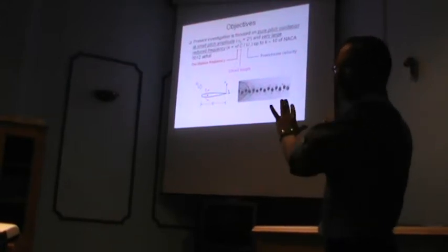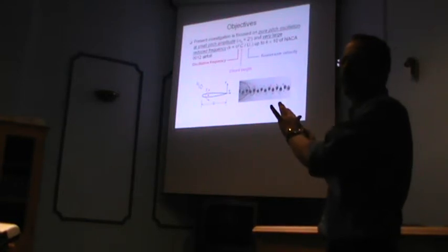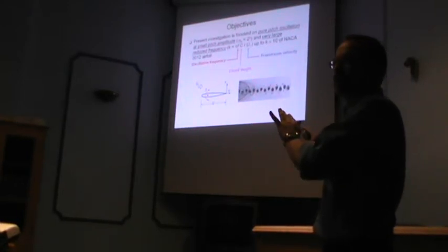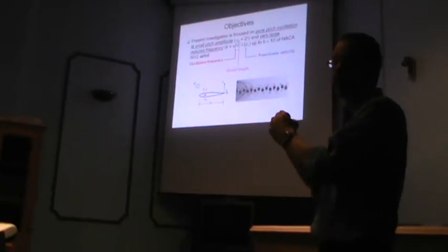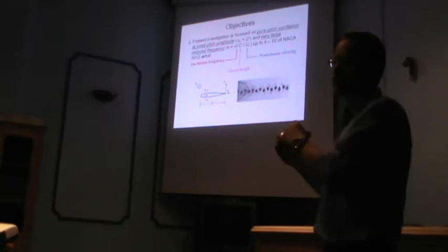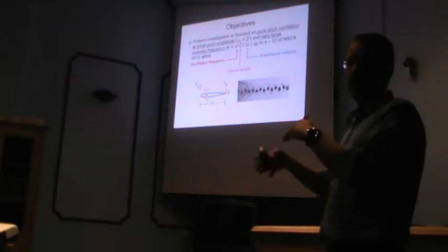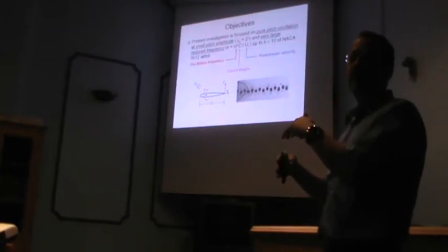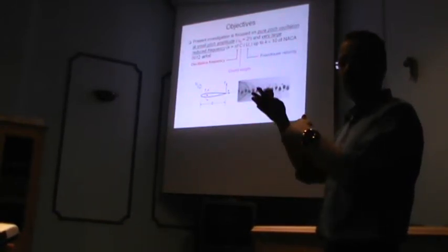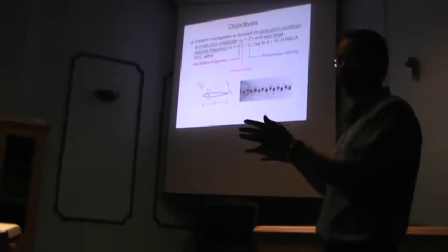This particular flow visualization image gave us the idea of why not try to model the wake using a train of vortex or an array of vortex structures. And if this is an effective way to do it, then we can use this to actually calculate the velocity field behind the airfoil, and then apply the integral momentum equation to calculate the net force, streamwise force that's acting on the airfoil.